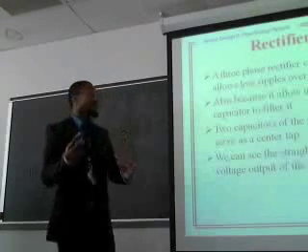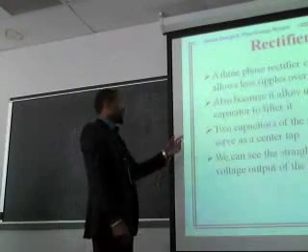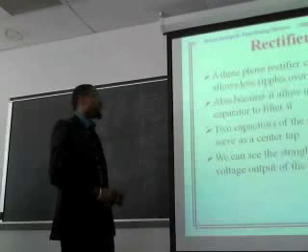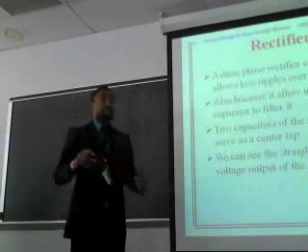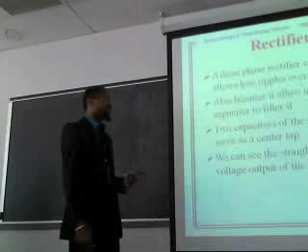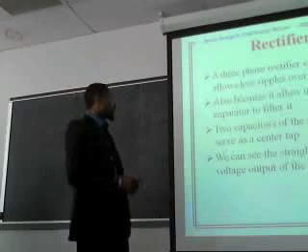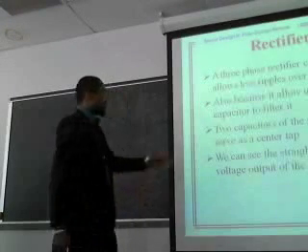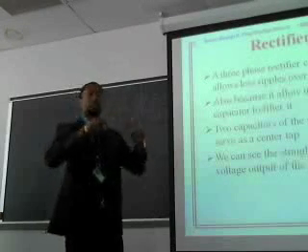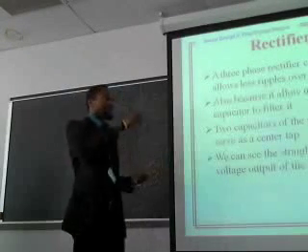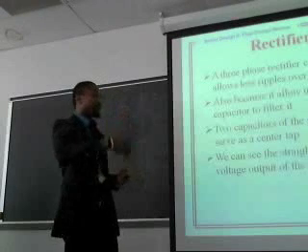We use the two capacitors of the same value to serve as the center tap. I still have to explain that in the next slide. Then you can see the straight line there shows the DC current, like from the scope. The straight line right there represents the DC current going through. That's the output.